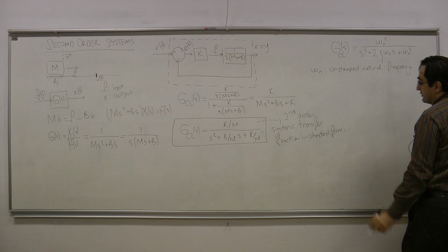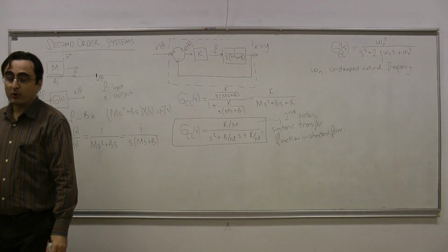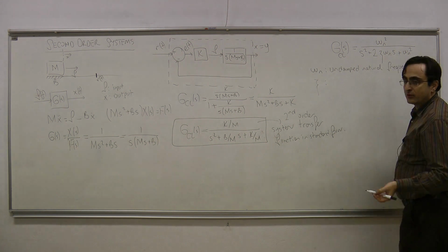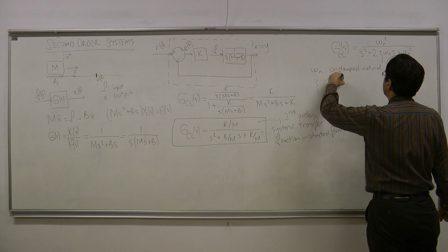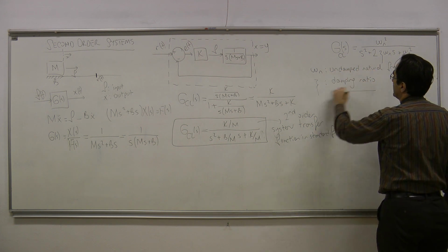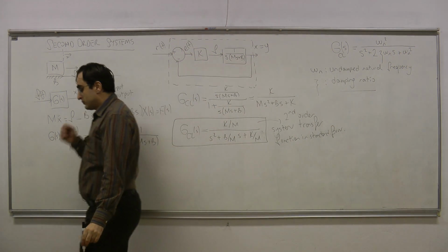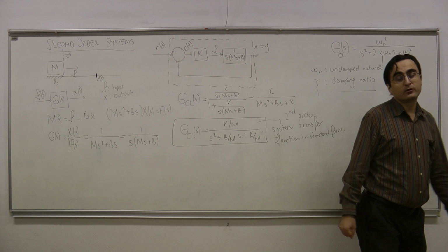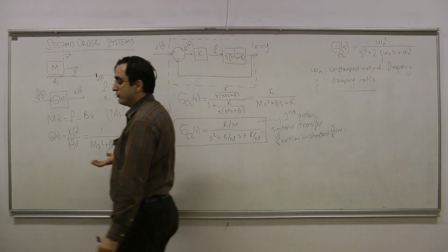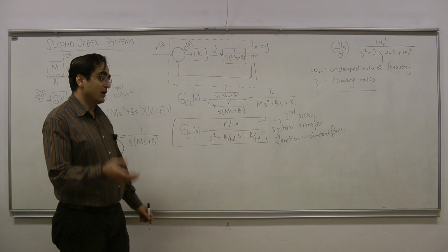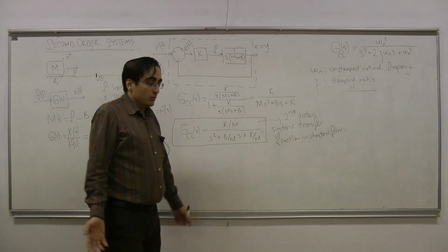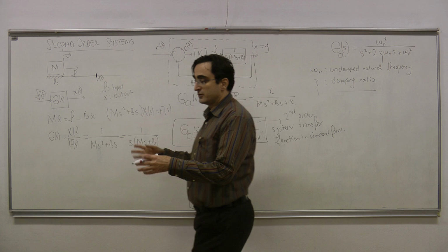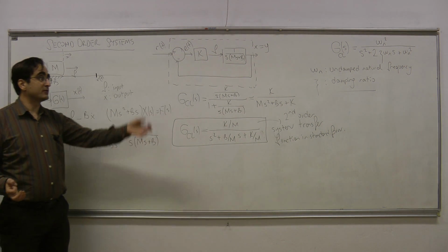Okay? And the second parameter here is going to be the more important one of these two parameters. So this is the letter psi. This is called the damping ratio. In Turkish it is sönümlenme oranı. So this parameter is also important, and this is determining the damping of the oscillations in the system, as we are going to see. So if this damping ratio parameter is large, then that means that there is a large decrease in the oscillations in time. Or when this is too large, then we are going to see that the oscillations would disappear from the closed loop system altogether. So we won't have any oscillations in the system if psi is too large.